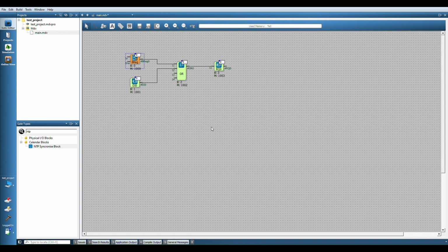First, we can assign a value by right-clicking on the binary register. When I send a 1, I see that the relay output 0 block is 1. Again, when I say assign value and click 0, we have returned the relay to the 0 position.